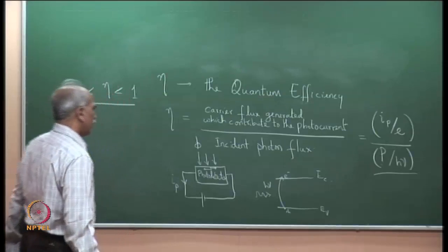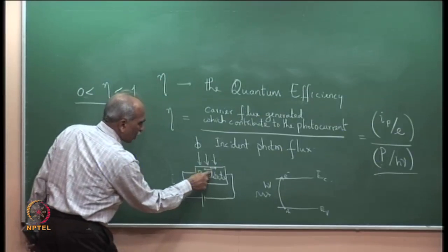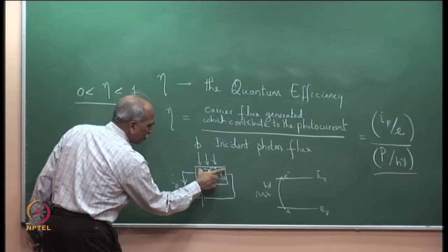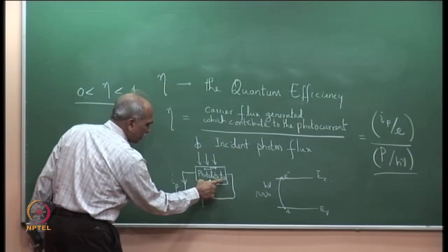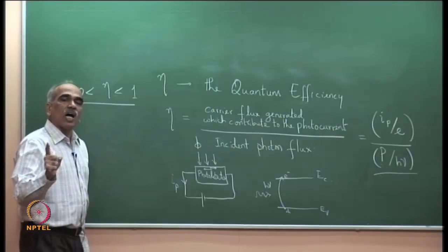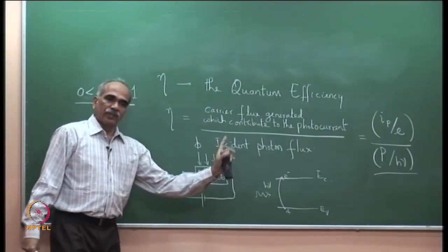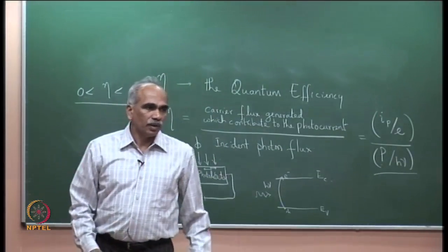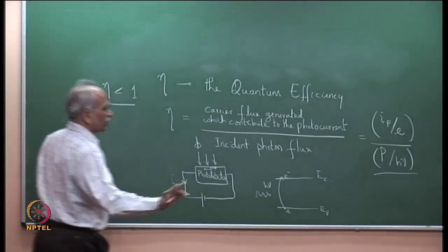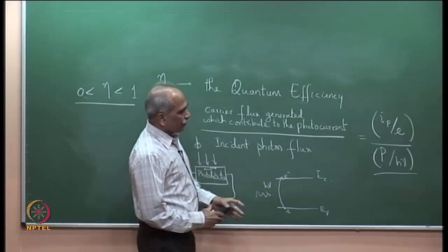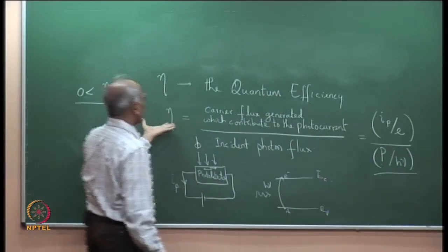The motion of one electron hole pair moving inside the semiconductor is equal to one charge e moving in the external circuit. This can be shown from Ramo's theorem. Depending on time we will get into that, but right now I hope this part is clear.